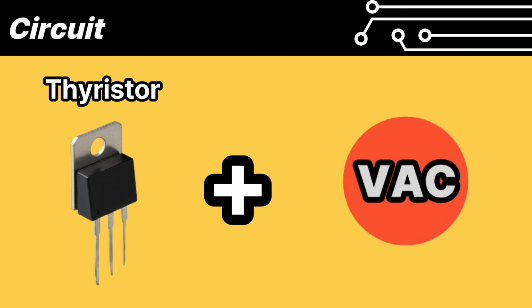Thyristors are suitable for circuits using AC power, such as AC motors or AC LEDs, because they can perform AC power control and have a high allowable current and high surge current. They can also be used in applications that use large DC currents.